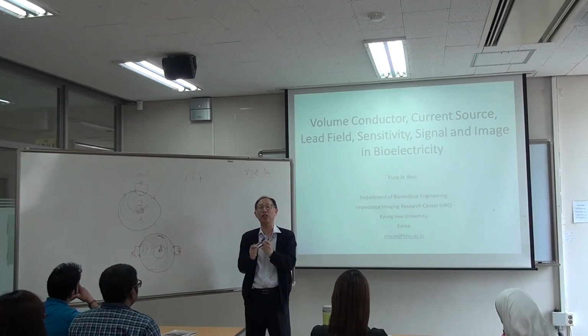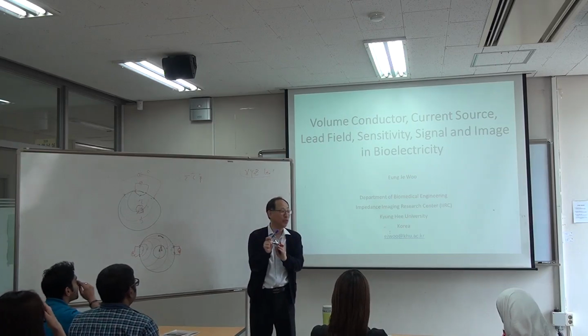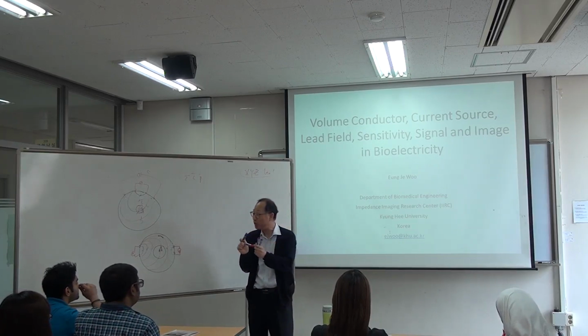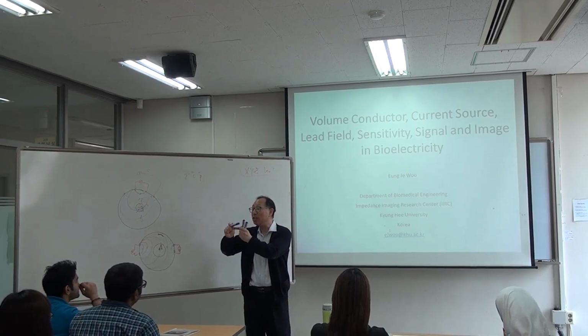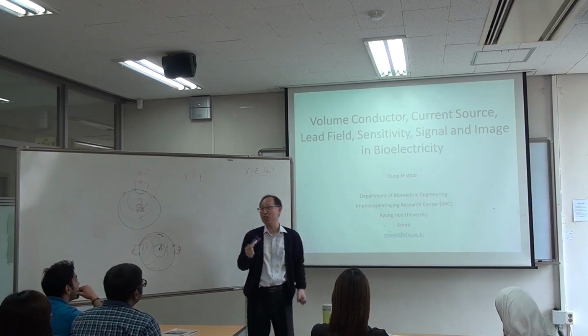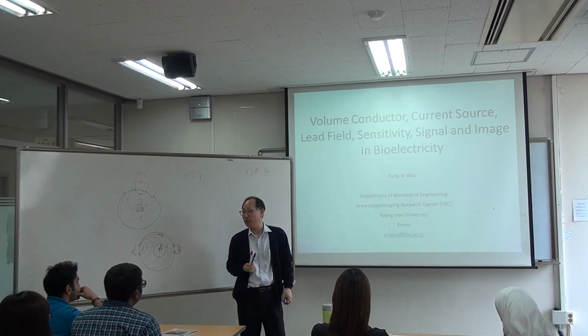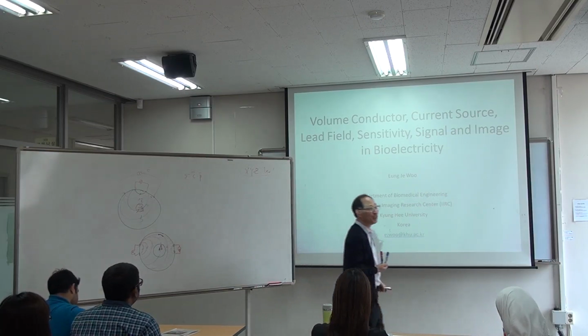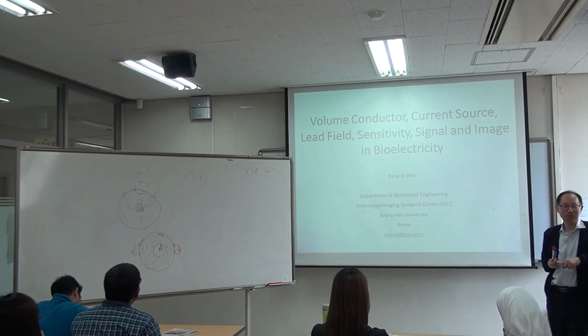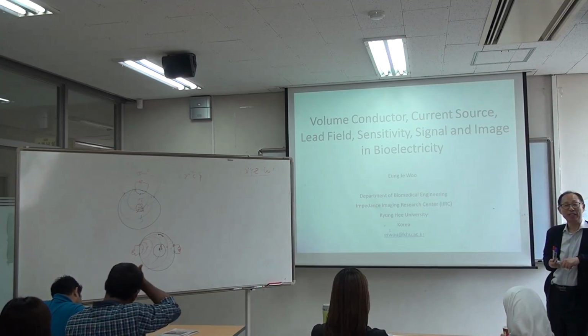If the inner product between the lead field vector and the equivalent dipole of the source has a similar direction and large amplitude, then that's going to be the best electrode configuration to measure that internal neuronal source current through the voltage on the surface.